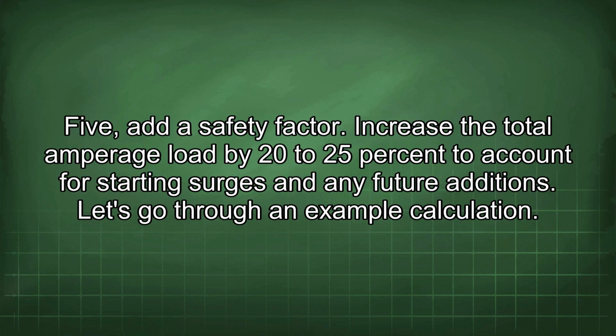5. Add a safety factor. Increase the total amperage load by 20 to 25% to account for starting surges and any future additions. Let's go through an example calculation.